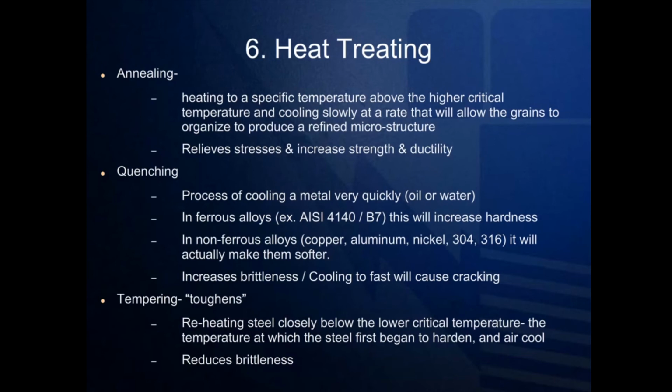Most applications require that quenched parts be tempered. Tempering consists of heating steel below the lower critical temperature, often from 400 to 1100 degrees Fahrenheit.